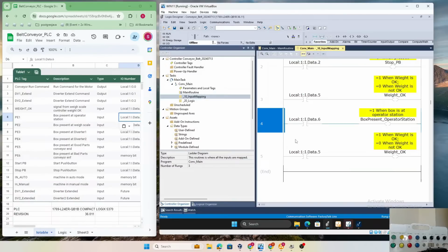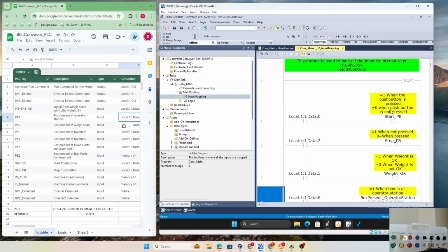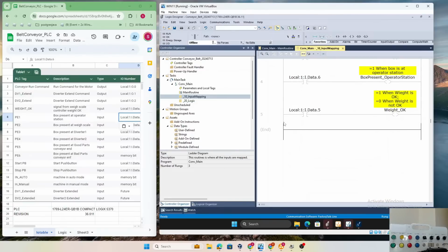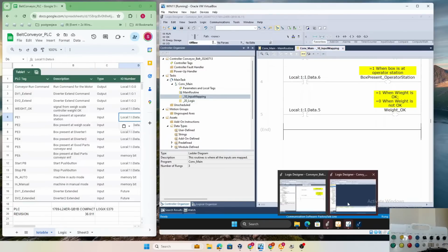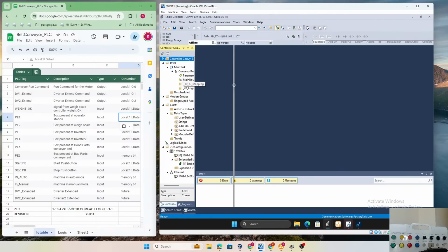The important point, the fundamentals, is we always want to describe what 1 and 0 means on that. This helps us avoid going and looking into the drawing: is this a normally open or normally closed contact that's been wired? It's always best practice to put as much detail as you can in the program, which will help the people coming behind you to look at the logic. So same thing here, we went ahead.